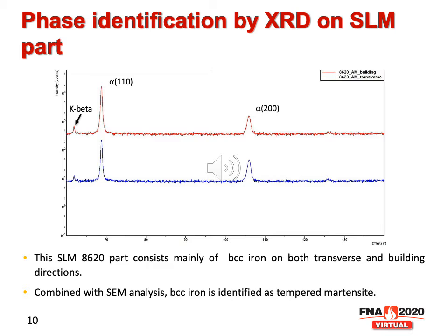During selective laser melting, due to the fast cooling during the process, we get martensite. However, the layer deposited before will be heated when we deposit the later layers. So the heat from depositing the new layer will temper the previously deposited layers. That's why we get tempered martensite.